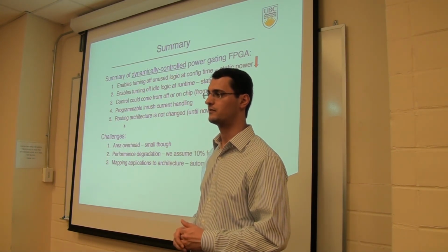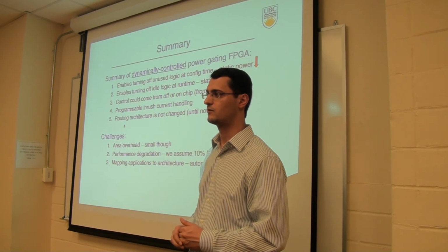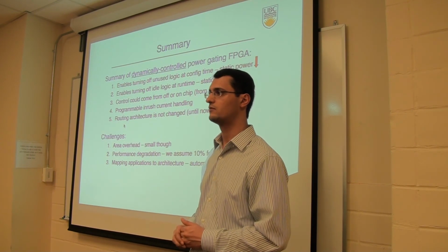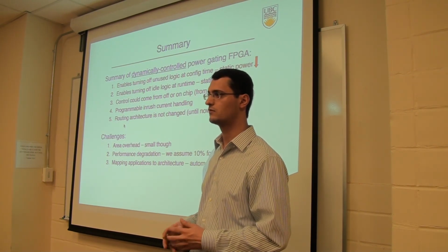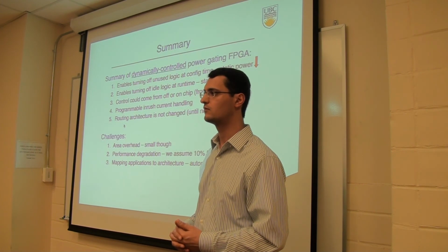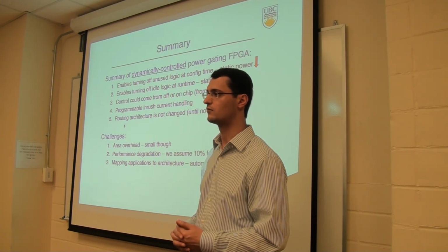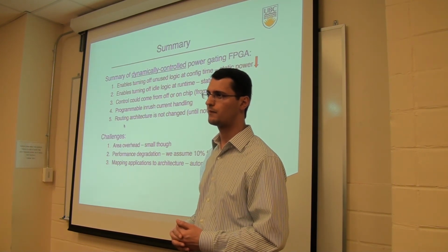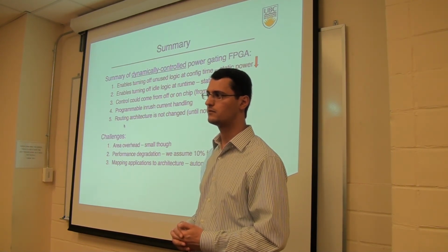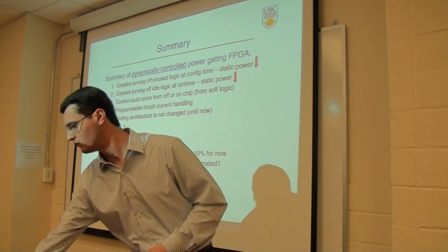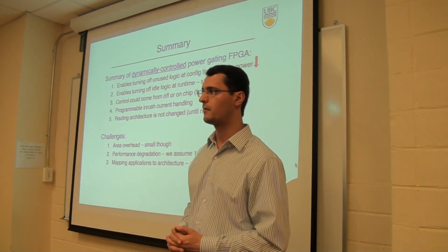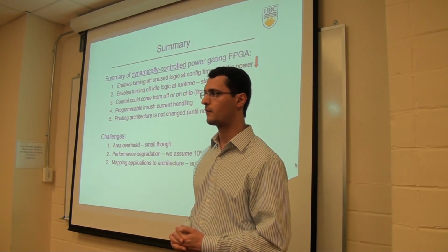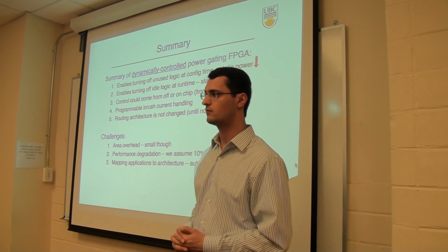And that's making me think that a slightly more fair comparison would be against those alternatives, just to give some sense, particularly if those were programmable, right? Like the programmable power lets you do that dynamic trade-off too, right? Power and performance and leakage power, when you pick the two threshold voltages with different body bias or something. That's what these folks do. So it is also dynamically tradable, and it's just a thought that might make an interesting and important comparison.